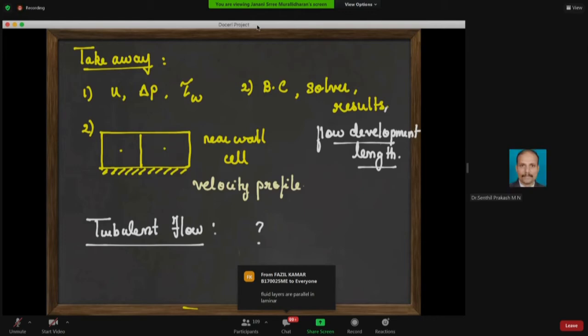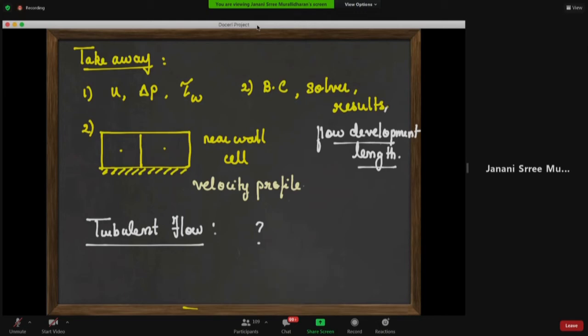And the heat transfer will be better in turbulent flow because chances of transfer are more in such a case, especially the convective transfer. Okay. So to quote what you are saying, turbulent flow is where particles move in a random manner, which tend to get a lot more mixed and hence enhances your heat transfer, right?